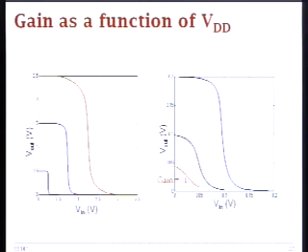So now the question is, if my curves look really nice, why don't I always use low voltage operation, right? Sub-threshold, that's one reason. Other reasons? What's the most important reason? Why don't you want to go this low? Performance? That's right, performance. You lose in performance, so you don't want to have really low voltage. What else is going on from what we've learned so far? How about noise margins? Noise margins decrease with VDD.